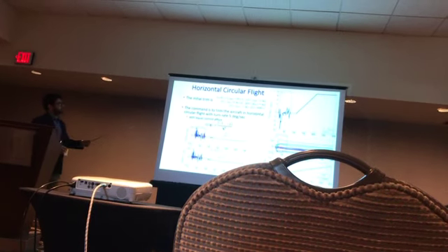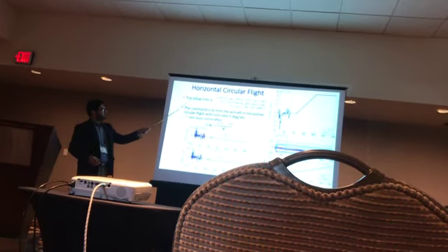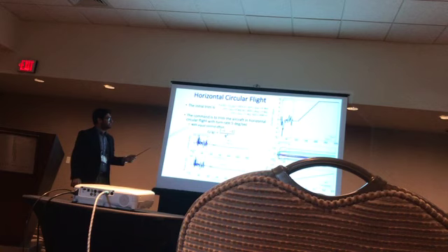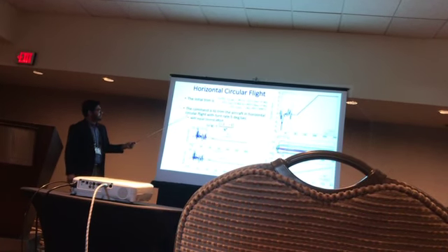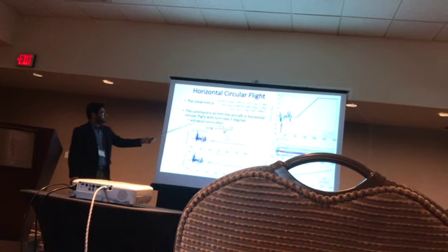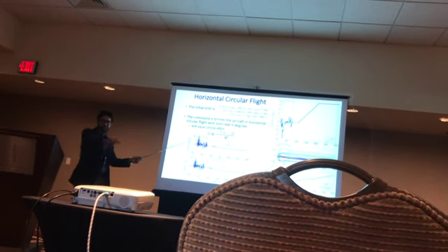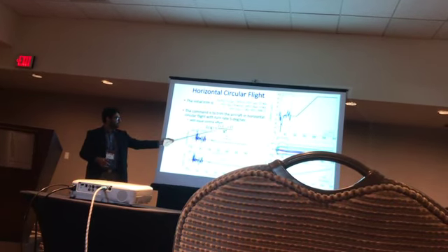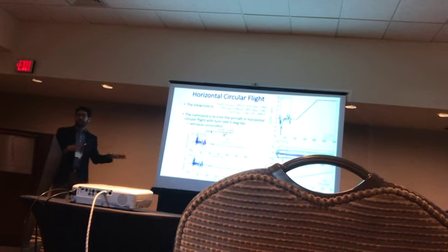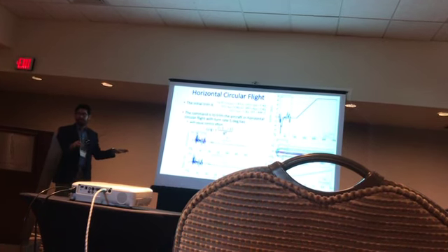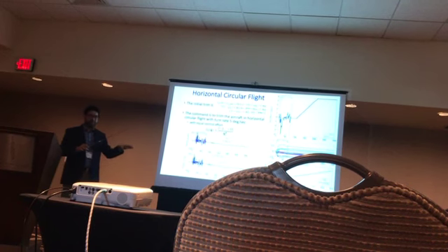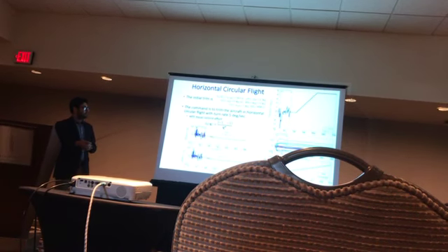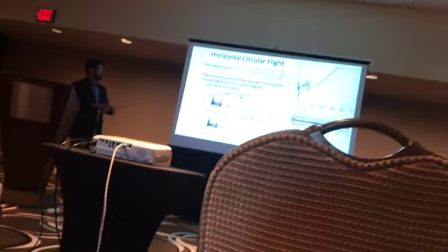So we assume that the aircraft is initially in a straight line. So forward velocity is constant. All other angle rates are 0. We ask the aircraft to go to another trim where the turn rate is constant at 5 degrees per second. So it's basically always turning in a circle. And then we set the filter coefficients to be 1, 1, in the ratio 1:1. So that means the aileron and the rudder are going to be used in the same ratio. So the control energy, in a sense, which is being requested out of the aileron and the rudder is exactly the same.